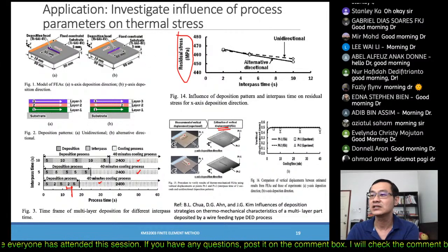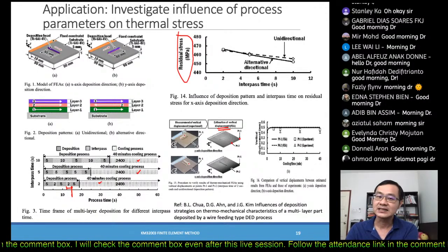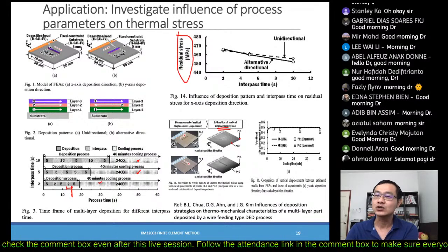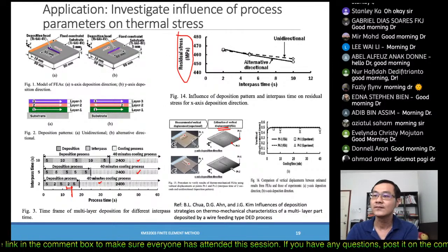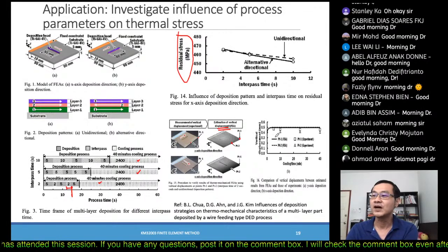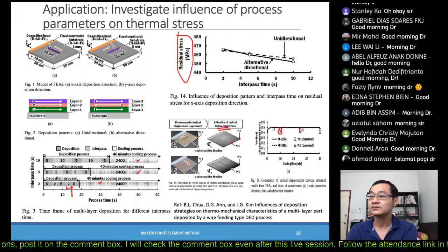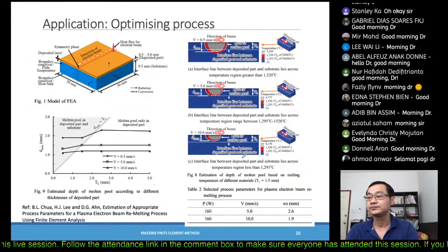In this case we just take 2 points, we measure the vertical displacement at these 2 points, and we did one experiment to validate that this whole simulation model is proper. All right, so we measure these 2 points, and we run the depositions, and we found it is very close to the experimental value at different cooling points. So this is a 40 minutes cooling process, right.